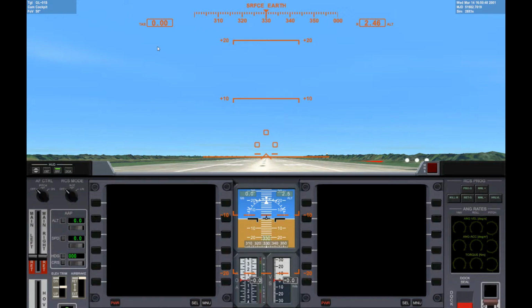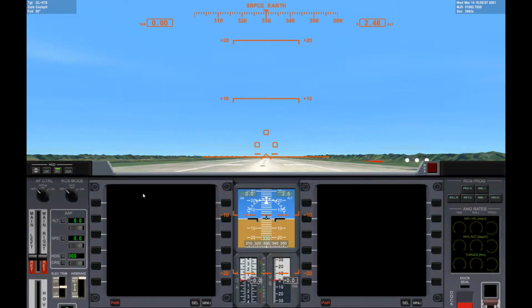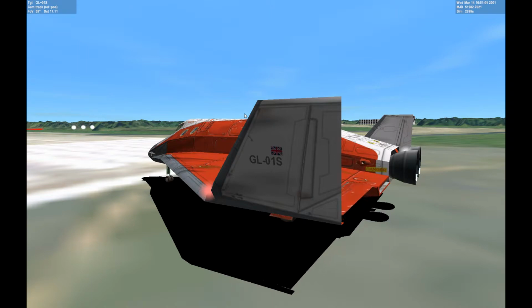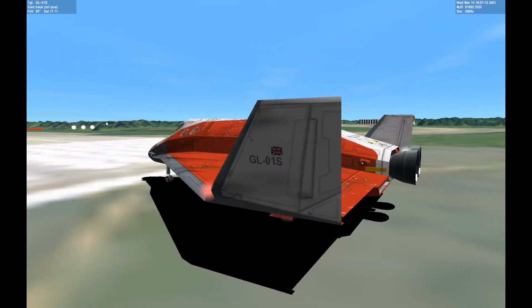Okay, this is your air flight control surfaces mode. Right now I don't have any selected, which means if I go outside, even though I have control of this craft, if I start moving my joystick around, you won't see anything moving. If I set it to pitch, you will be able to see the elevator moves, but you won't see the ailerons moving, and you won't see the rudders. If I do on, now we can move everything.